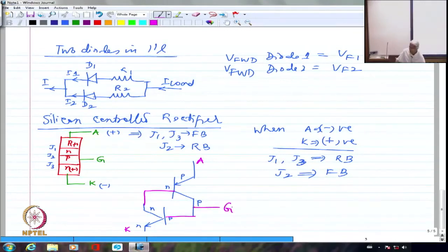So if I don't give any power supply to the gate, if I don't forward bias it, I'm not going to have this transistor conducting at all. But the moment I actually inject a gate current into this, or if I forward bias this, then this transistor is going to conduct. So I'm going to have the base flooded with a huge amount of charge carriers. The emitter is heavily doped, so I'll see a huge amount of electrons coming in, and then that is going to go through the collector and that is going to flood the base of the next transistor.